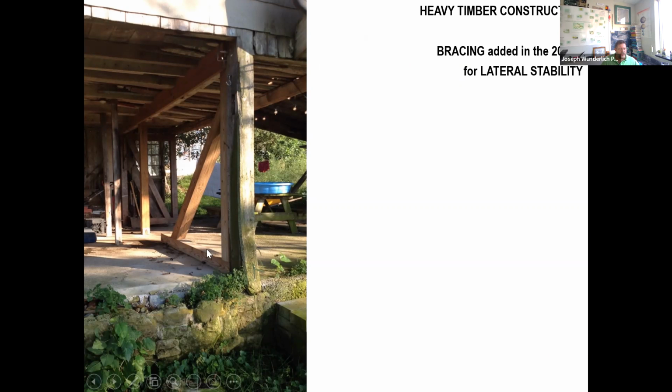5,000 PSI concrete with anchor bolts, and then this heavy timber pressure treated. This is all new, and then lag bolted to this main structural support and column here, and then also sistering on a beam here, a girder to hold up the old barn, as well as a truss that I originally built over here when I first moved in. It's weathered, you can't really see it so much, and a new column, also anchor bolted into the ground.